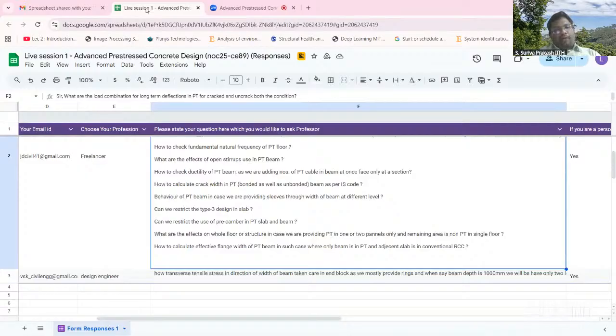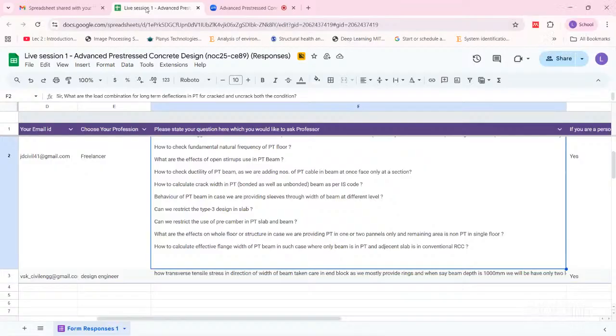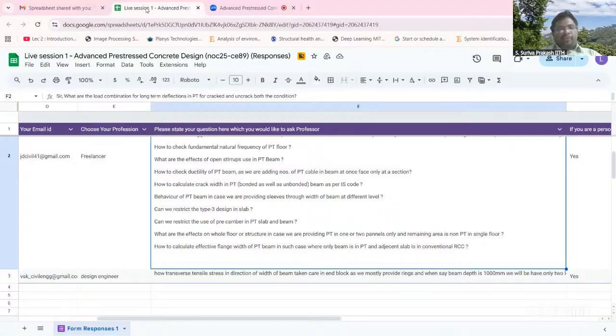that tells you, after you do the moment curvature analysis and find your strain, how to use that strain to get your crack width. Okay. Strain multiplied by the crack spacing will give me the crack width. Now, how to find the crack spacing? There are some empirical formulations. We'll share some 2-3 pages of that PDF document, because I cannot share the whole book, it's against copyright, right? So we will share it with all the course participants. You can look at how to do that.